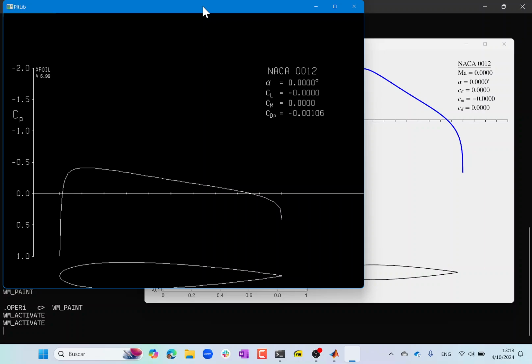So alpha 0 basically specifies the angle of attack at 0. What we get right now is the pressure coefficient distribution on this airfoil. Again, like what we said in class, the lower side has a higher pressure coefficient. The bottom of the scale is 1.0, and the horizontal line is 0, and the further up you go, the smaller the pressure coefficient is. And the negative pressure coefficient is correlated with positive speed.